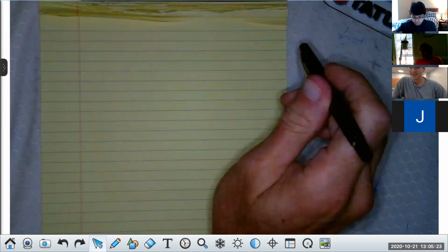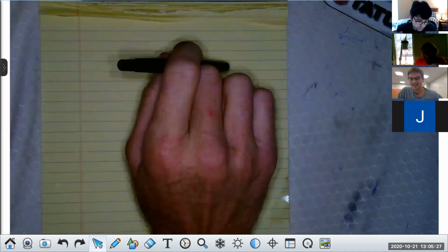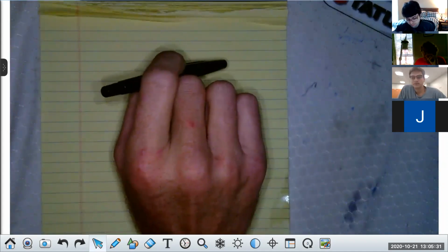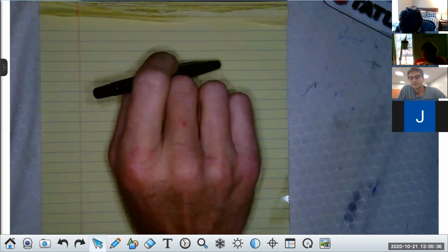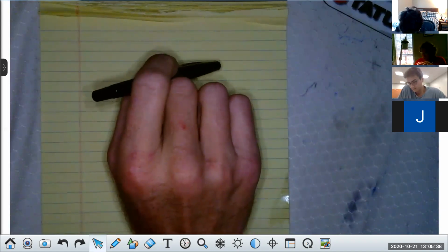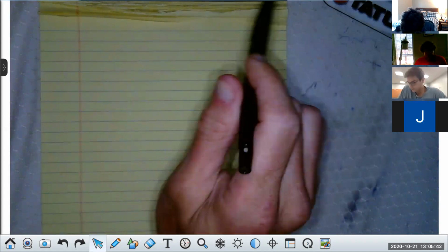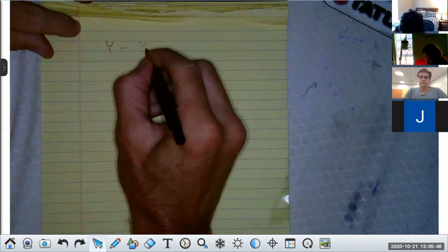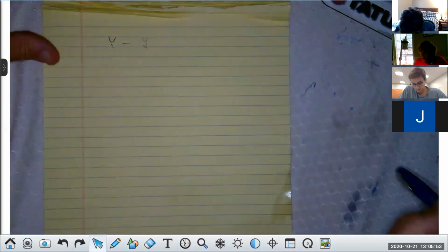Now, I got to tell you one other thing too. With delta Y configuration of systems, I'm going to go through this for a very important reason. People mess up delta and Y often by the transforms. I always tell you this, and I'll say it again, we always do everything in the Y configuration, and then we get whatever information they want. You will not go wrong doing it that way. Does everybody hear me?